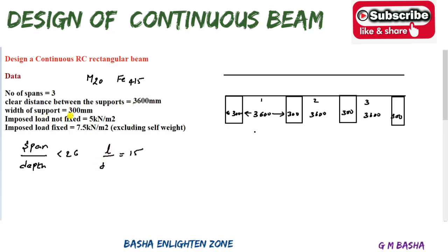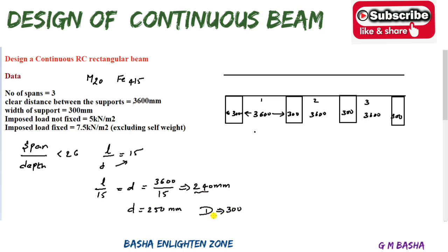What is your L? L is the clear distance between the supports. Therefore I will cross multiply: L by 15 equals D. L is given as 3600 mm, and I will select the 15 range. If you simplify, you will get around 240 mm, so the effective depth will be around 240 mm. Therefore approximately I will take 250 mm for my design purpose, and the overall depth will be around 300 mm. If you want, you can choose effective depth 240 and overall depth 300.